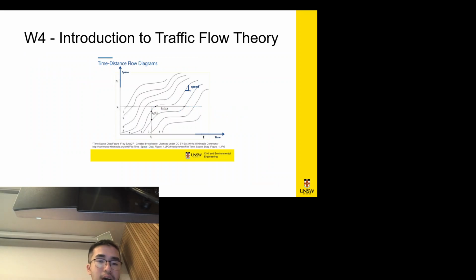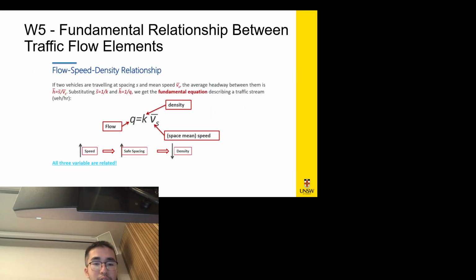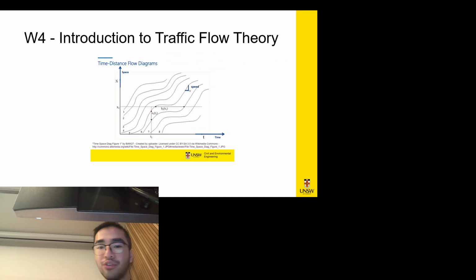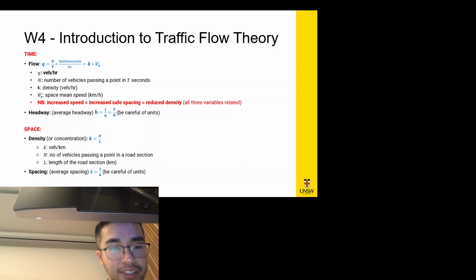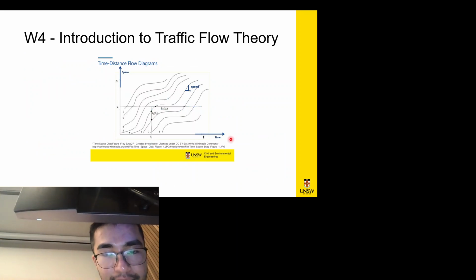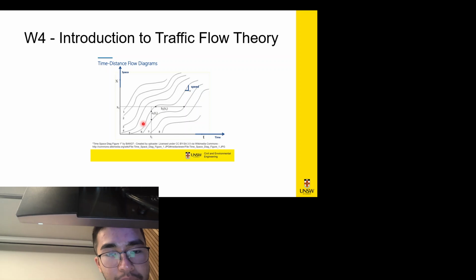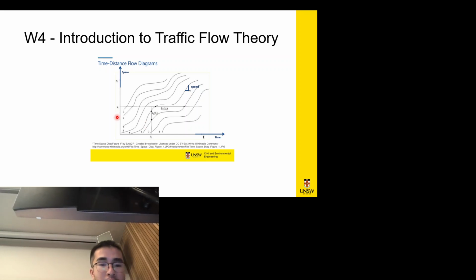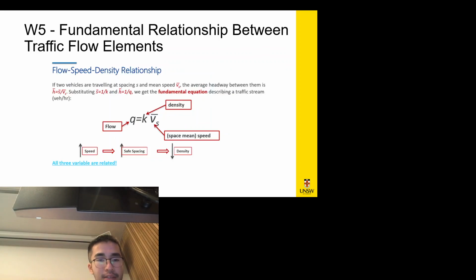You'll also be introduced to time-distance flow diagrams, and the relationship with spacing and headway. If you have time on the x-axis, the difference between two vehicles horizontally would be headway, and the spacing would be vertically on the y-axis.